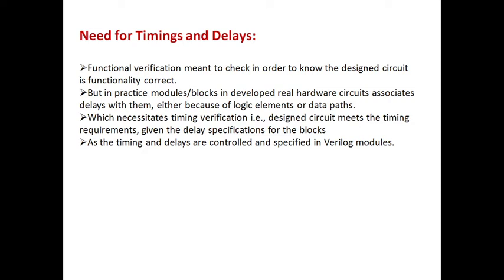As soon as I send the input signal, I cannot expect the output signal at the same instant of time. A certain amount of time will definitely elapse, and after that the output will be exhibited. So the real hardware circuit associates delays with them, either because of the logical elements, as I have mentioned, and also because of the data paths.